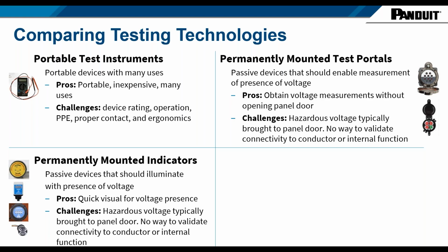And then again, very much like permanently mounted indicators, because they're a passive device, they have no way to validate that they are still connected, and there's no way to validate the internal function, that nothing has failed inside the device. Going back to high vibration environments, many of the environments that these devices are installed in are not very clean or very stable, with no oscillations or vibrations, right? So there are failure points, and there are still mechanical and electrical pieces in there, the resistors and solder points and PCB boards, all of which, if they fail, there's no way for you to verify that it is still functioning properly.